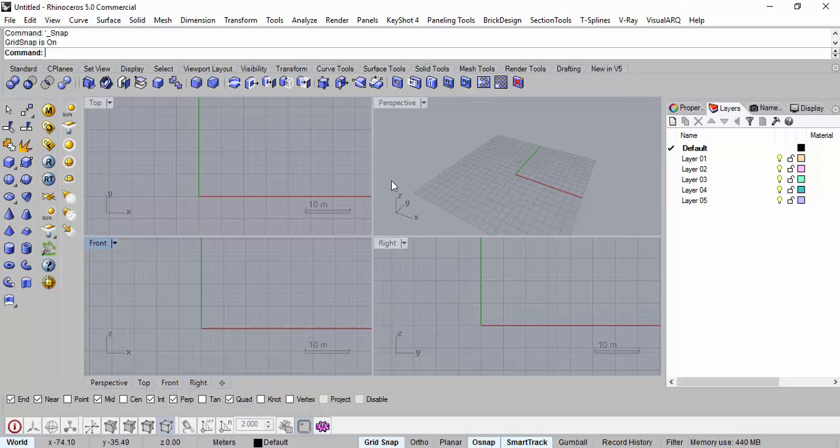This is a real world coordinate axis where X is always in this direction, Y is perpendicular to it, and Z is always in the height space, right? Whereas here, this is a construction plane, so these kinds of planes are used only to draw in 2D, right? To draw in X and Y dimensions. Are you getting it? It has nothing to do with your world axis.